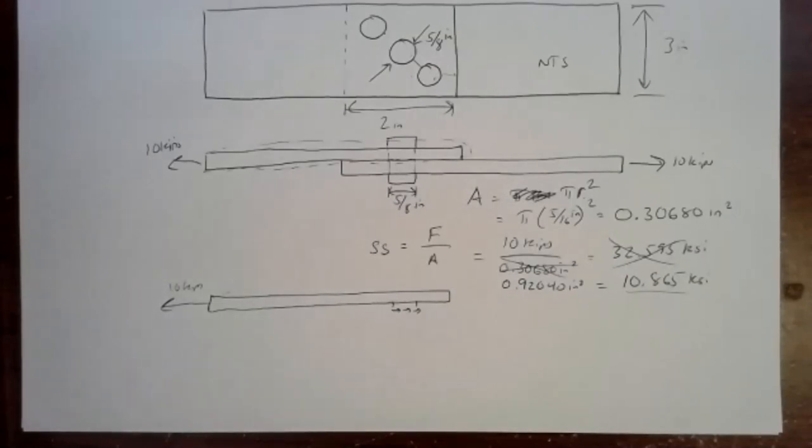But because we want to make things small, we want to ride those limits close, but not go beneath them. That's where we tend to ride a little bit close to that edge distance, usually not right on it. We want a little bit of margin there for future repairability and things like that. But the details of the layout only really matter when you get close to those limits. As long as each rivet is far enough apart, you could shotgun the thing. It could just be a whole bunch of holes with no pattern at all. As long as none of the holes are close to each other, it'll still work.